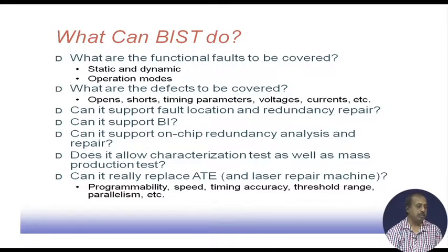So, that is an important issue. There may be static or dynamic mode faults, there may be operation modes. What are the different operating modes that the RAM, the memory, has? What are the defects, like open, short, timing parameter, voltage, currents? What are the defects we are going to cover? Can it support fault location and redundancy repair?